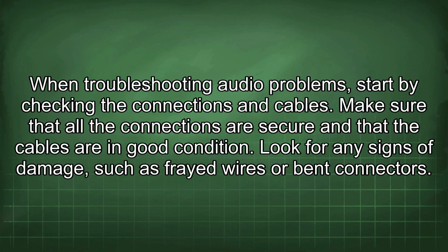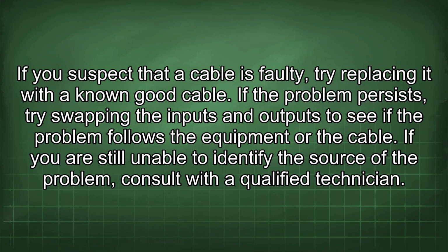When troubleshooting audio problems, start by checking the connections and cables. Make sure that all the connections are secure and that the cables are in good condition. Look for any signs of damage, such as frayed wires or bent connectors. If you suspect that a cable is faulty, try replacing it with a known good cable.